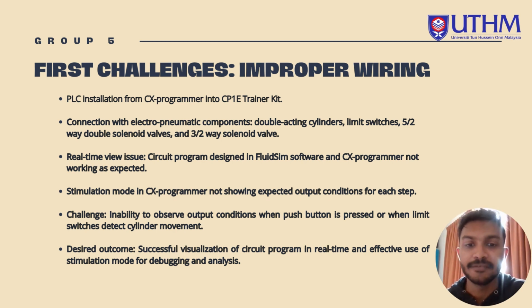the circuit program designed in FluidSim software and CX Programmer software does not work as expected. So what we design, how we execute it, how we install it, and when we run it, it doesn't operate properly as we wanted. So we troubleshoot them. One thing is that CX Programmer software has its own features, like simulation mode. We can observe whenever we press the real-time buttons, which button we are pressing and which cycle is going on now.